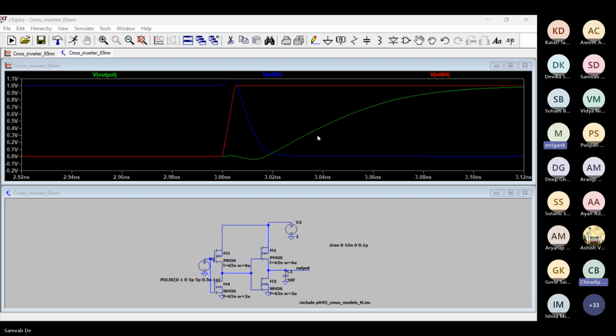No, in this simulation there is no probe capacitance. Whatever probe you put is ideal. In actual circuit testing, yes, the probe has an effect. Its impedance and capacitance matter, and it will load the circuit. Here in the simulation, it will not have any effect.